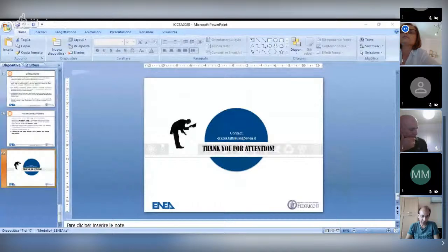Okay, thank you for your question. Well, a continuous set of PM 2.5 distribution on the built area was generated using the geostatistical ordinary kriging interpolation technique, based on the data set of the annual average of PM 2.5 concentration gathered by the regional station network of ARPAC.